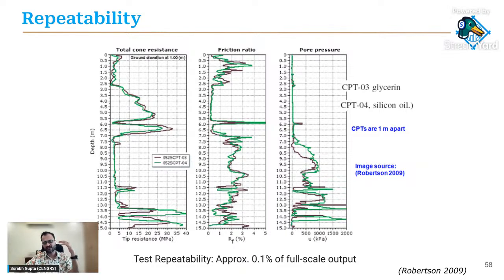Now, this is very powerful, because most of us, myself included, who are used to dealing with SPT, are used to accepting that there is a lot of intrinsic variability in the SPT values. We were used to seeing a 20 to 30% spectrum of SPT values, even at the same location, depending on who's the operator, how the test was done, and which company did the test.